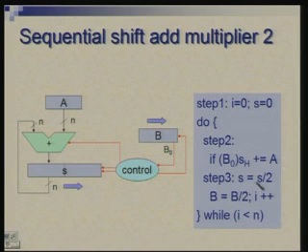Although I have introduced this as another step, it is actually possible in principle to do all this in a single clock. I will not go into details, you can just take my word for it for the moment, but it is possible that the final value which has to be there in S as a result of summation and shifting, you can actually look at that and place that in S directly in a single step. So, that is not very difficult, but just for conceptual clarity, we assume that first A is added, and then shift is done.